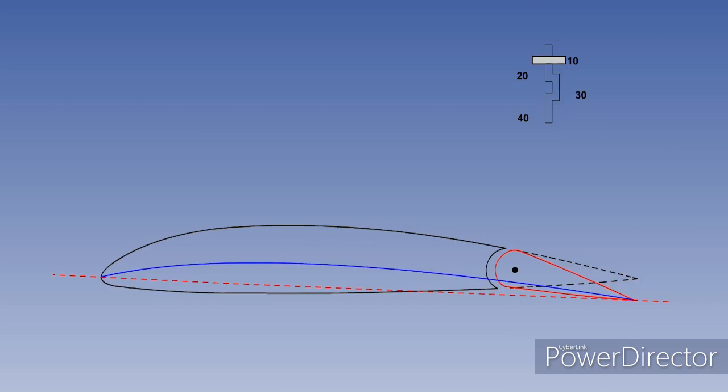10 degrees of flap will be ideal for takeoff, because CLmax will be increased a moderate amount, but drag will increase only slightly. Prior to landing, flaps should be selected in small increments, and 10 degrees would be the initial selection. It should be noted that any amount of flap will increase drag. The significance of this fact will be explained later.